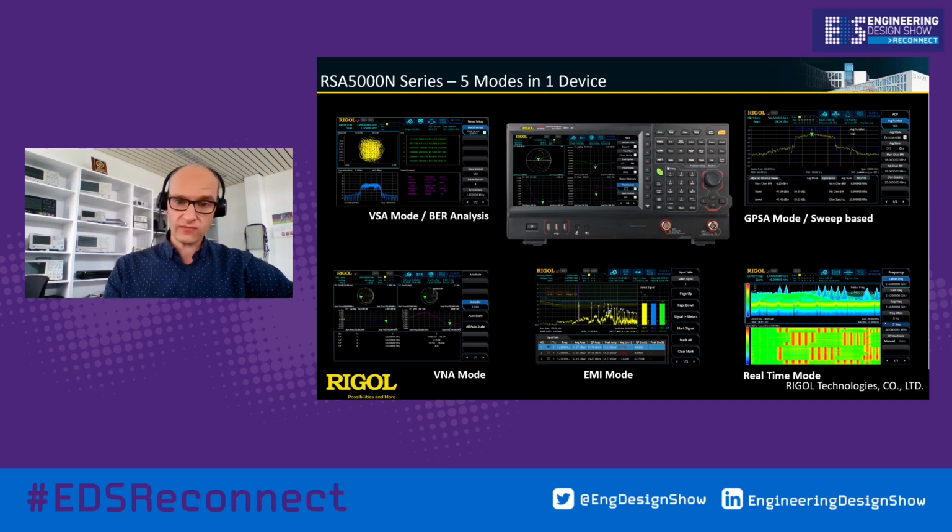We have a vector network analyzer for S11, S21, and distance to fault parameters which can be tested. And we have a vector signal analyzer mode for tests for digital demodulation and bit error rate analysis, which we're also using for further tests in this presentation.